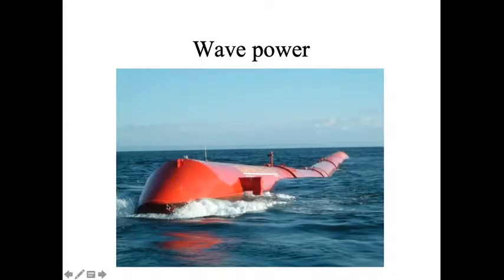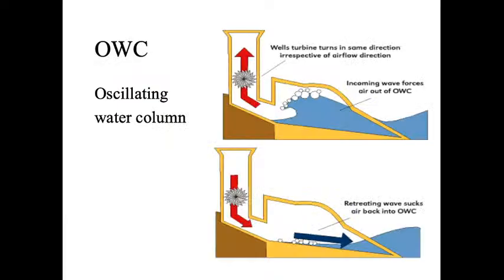All right, wave power. This is a less known one. We have an oscillating water column, which traps the wave inside of this uniquely shaped and designed column or chamber. That's going to produce higher air pressure. It's going to compress the air, shoot air through a turbine that's going to spin, and as it spins, it'll power a generator.